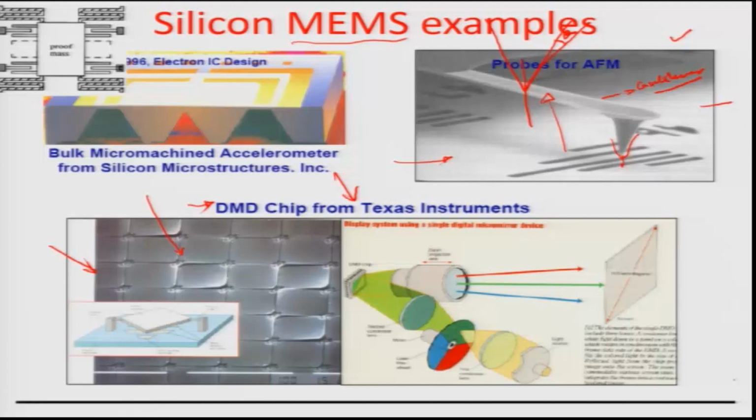All these mirrors are probably a few microns by a few microns in width, and each of them is capable of twisting and deflecting, so that the cross section of the mirror is represented somewhere here. Each of these mirrors is pivoted and standing on two pillars, as you can see, and these mirrors are able to get deflected through electrical fields, which are a function of the discrete electrodes on the base substrate on which this particular mirror assembly is standing.